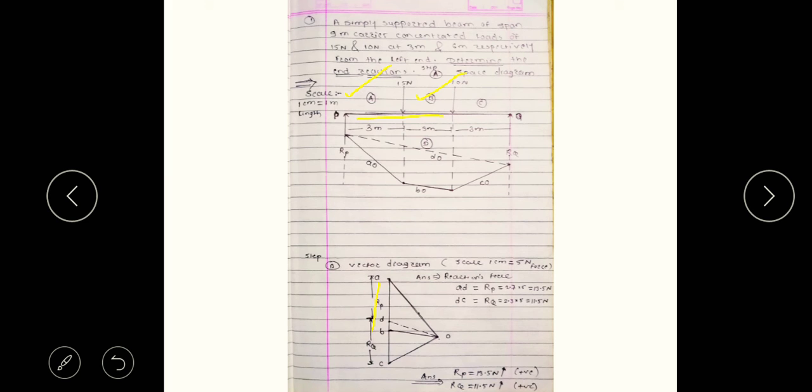So here we will see in a vector, this is the A point and the second is the B point. These two points indicate the 15 Newton force. So take the parallel component to the 15 Newton, and draw the line from A up to the B. Then the next thing, come to the second force.